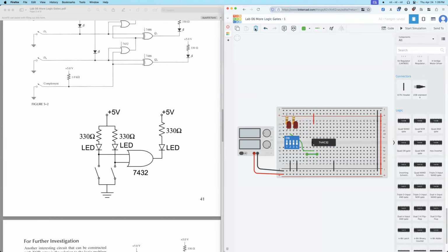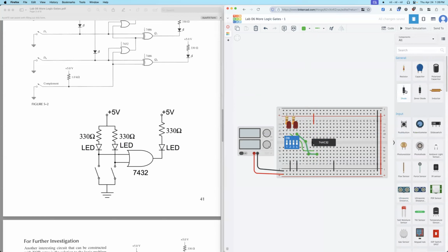Oops. So, okay, it's from here. Okay, so this is pin 2. Then pin 3 is output. So we need a resistor and LED again. Resistor, maybe from here. So 330. Then LED.